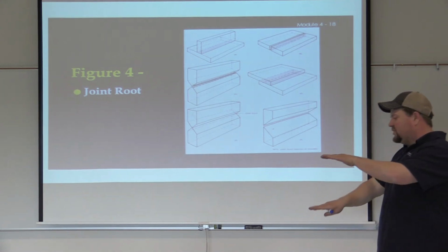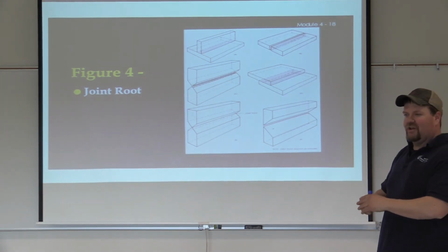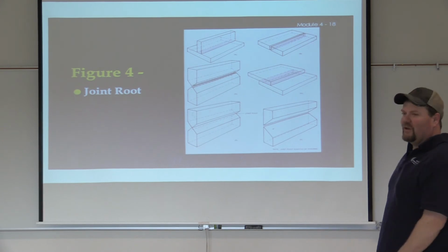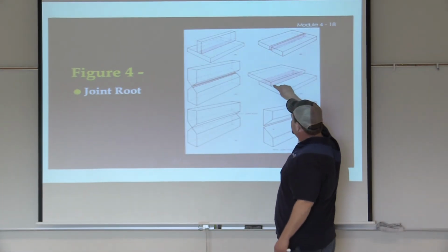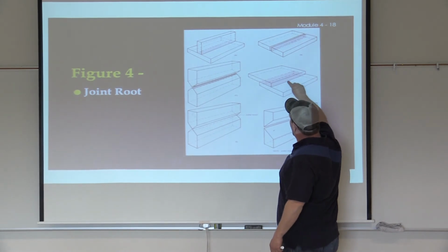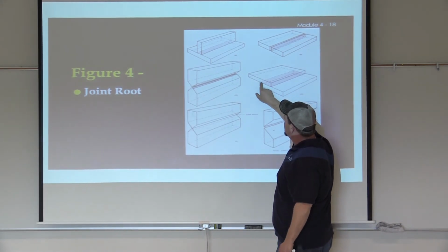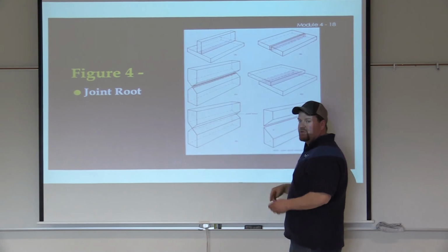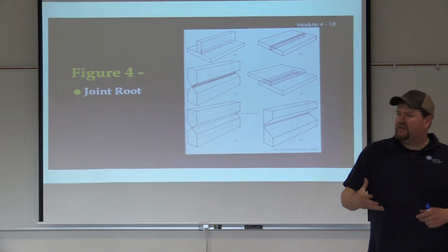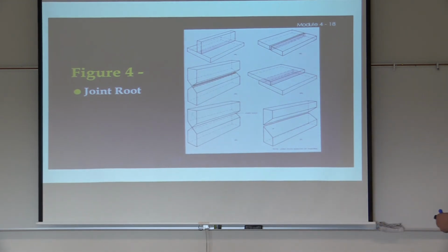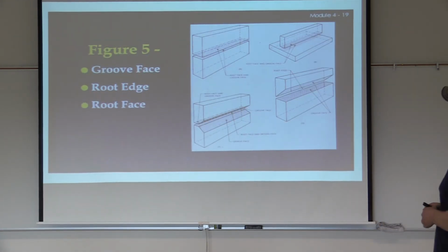So sometimes just a piece of steel on steel is going to show a root, and you're going to think, there's not really a root there. It's not like a butt groove, but it is. The root happens to be these two places right there, that line where they meet. In this case, on the edge weld, it's where two lines meet as well, okay? Root's pretty easy for the most part. We can see where the two pieces meet. This one's not very confusing.